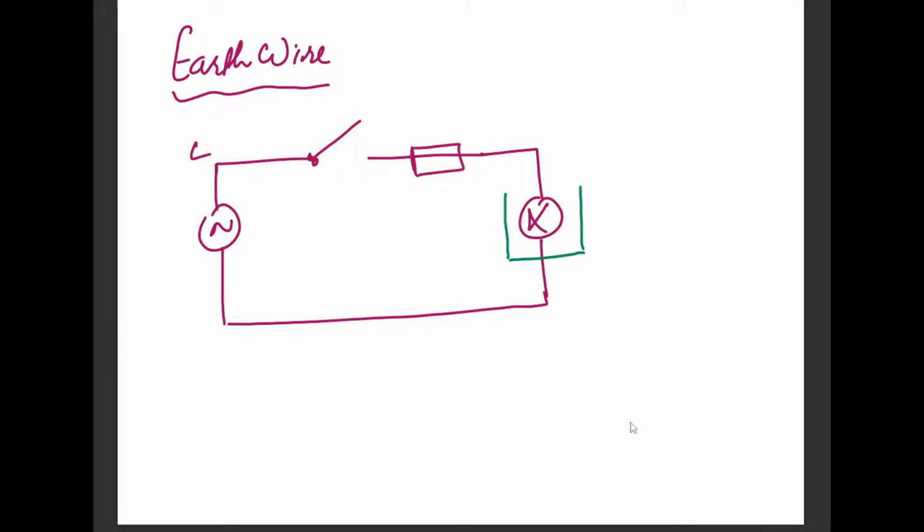Based on an anticipated accidental condition, it's possible that sometime later in life, because we're constantly using the wire, due to the bending effect of the wire and its own stresses, it undergoes a damaged insulation problem. If that occurs, the live wire may come in contact with the metallic part internally. You may not be able to see this from the outside of the appliance. It may happen internally, and you don't know that this has happened.